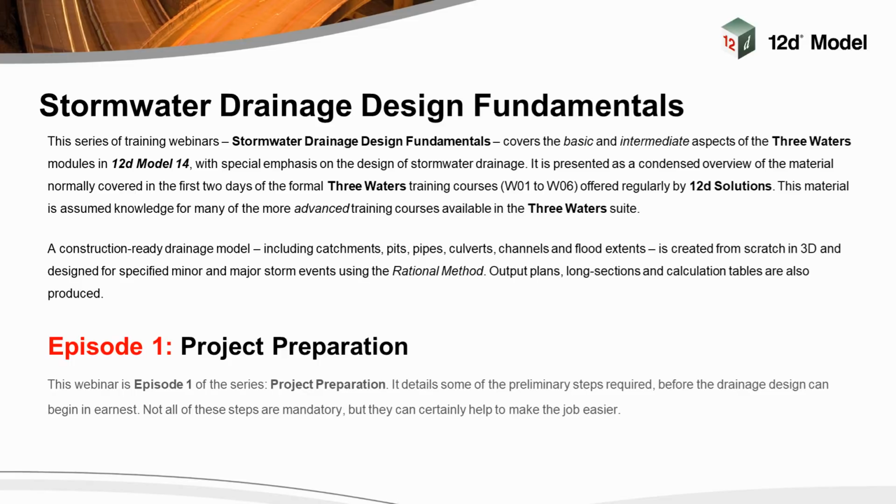So in this series, I imagine it is going to go over about half a dozen episodes, and this will be the pilot episode, I guess, so hopefully we don't get axed along the way. Throughout the series we will be creating a construction-ready drainage model with catchments and pits and pipes and culverts and channels and flood extents created from scratch in 3 dimensions and designed for specified minor and major storm events using the rational method. And along the way we'll be producing output plans and long sections and calculation tables as well.